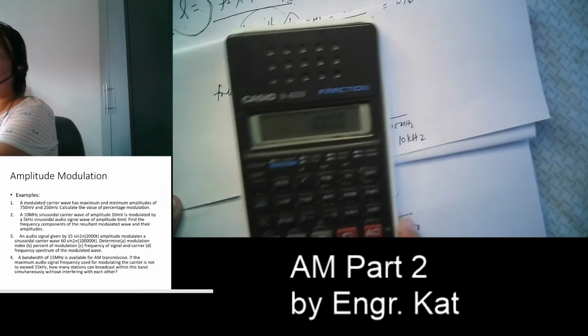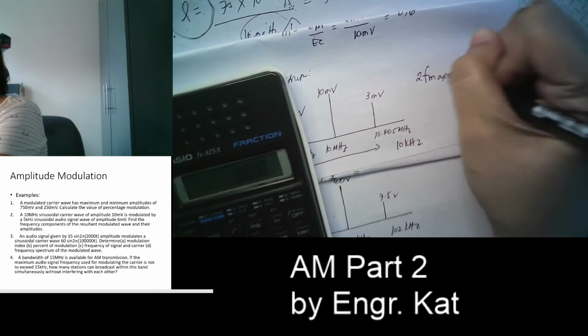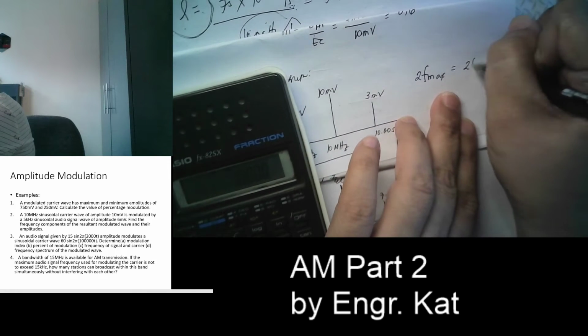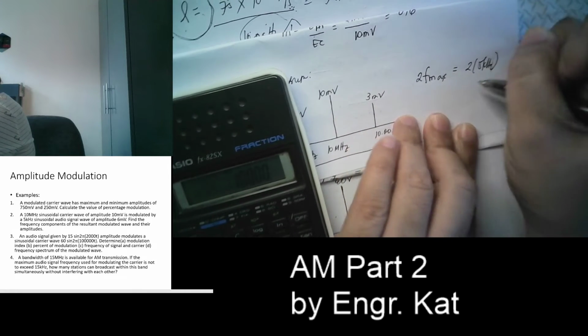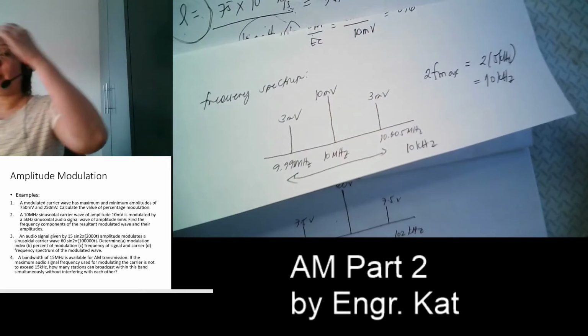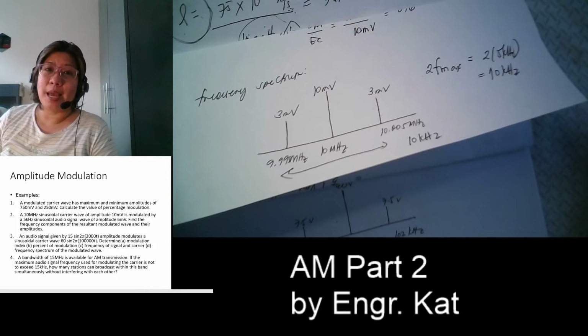Or it is said that your bandwidth also is 2 times FM max. So your FM is equivalent to 5 kilohertz. So 2 multiplied by 5 kilohertz will also give you 10 kilohertz. So the problems in AM are just as simple as that.